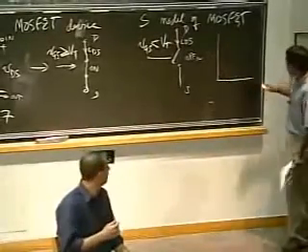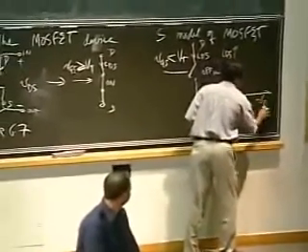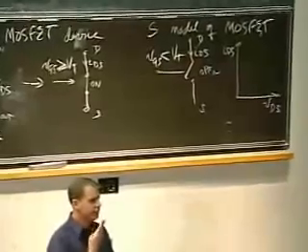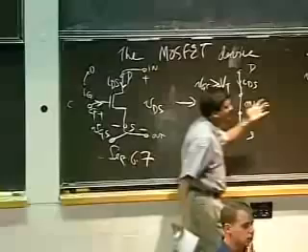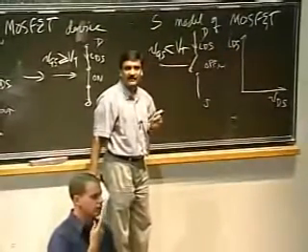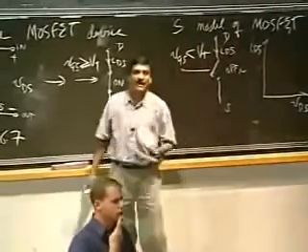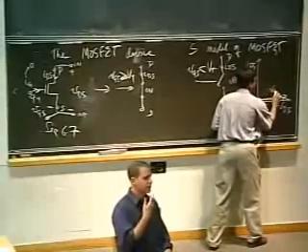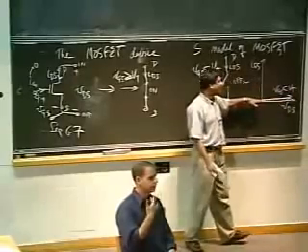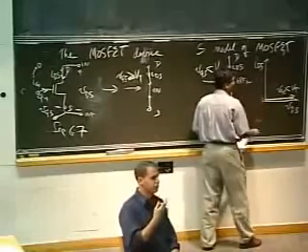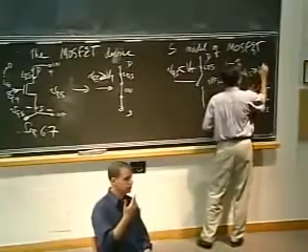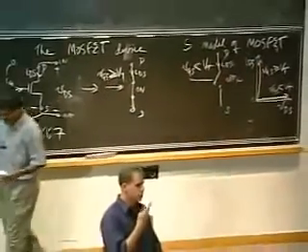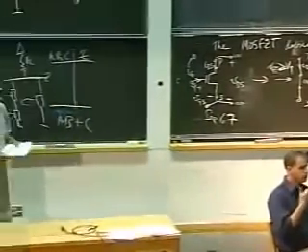So I can plot the following. Much like I plotted the IV characteristics of two terminal elements, I can plot the IV characteristics of this three-terminal element in the following way. I can focus on two terminals and look at VDS and IDS for that terminal pair, and draw the curves for how it will behave as I change the VGS that I applied. So what I'm going to show you is that if VGS is less than a threshold, then this behaves like an open circuit. So no matter what the voltage is, the current is 0. Similarly, if VGS is greater than or equal to some threshold voltage, then I get the IV curve behavior of a short circuit where the current can be anything and controlled by external forces like in any short circuit. Okay? So let me show you on the screen.